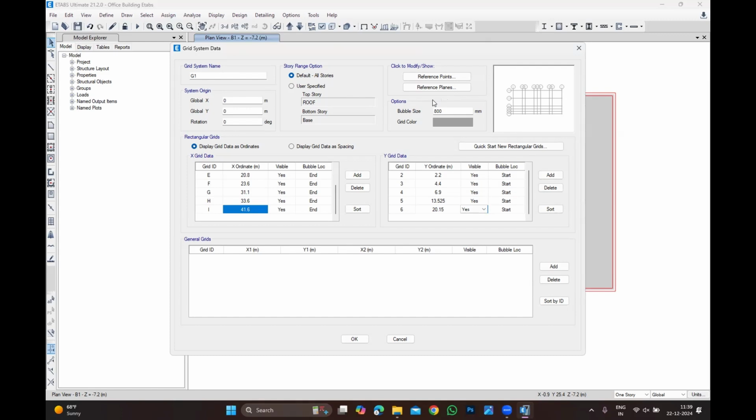What happens while creating the grid lines is you will face a problem. While measuring some dimension, you will face problems because then you always have to use the calculator, with values like -2, -5, -3. If you keep it 0, it is easy. These are some modeling tips to save your time. That's all. There won't be any kind of mandate. You don't have to go with this.